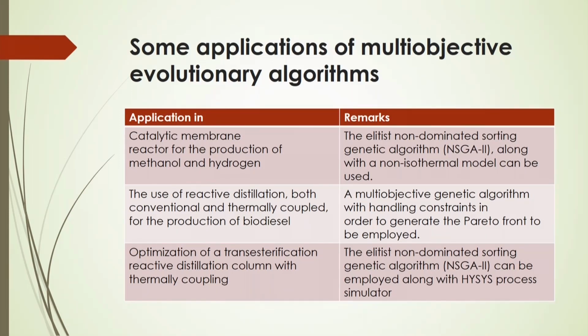Another important application is the transesterification reaction in a reactive distillation column. In that case, the optimization of that transesterification reaction in the reactive distillation column with a thermally coupled system can be done, and for that optimization the elitist non-dominated sorting genetic algorithm can be used along with the HYSYS process simulator software.